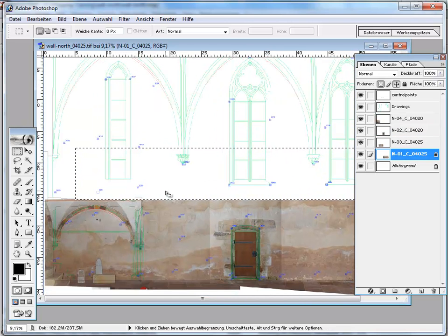You can change the colors, forms, etc. If you are finished with the picture editing, you can reduce the multi-layer TIFF file to one image layer, save it and load it back into Metigo map under a new project and read it in for mapping.